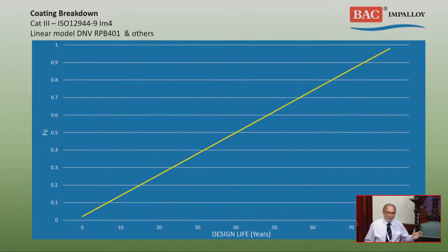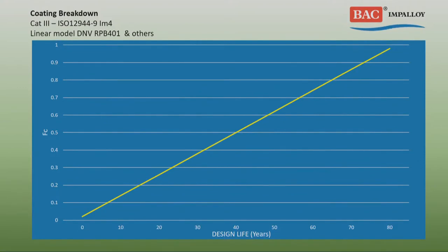Well, we know that seawater just absorbs into the paint film, and we know that when the seawater is absorbed into the paint film, it becomes less resistive. But we also know that the front, ahead of the absorption front, still remains resistive throughout the coating life. And we only get corrosion at the substrate when we have a conductive path from the open seawater directly to the substrate surface. So what might the real model, the actual model, be?